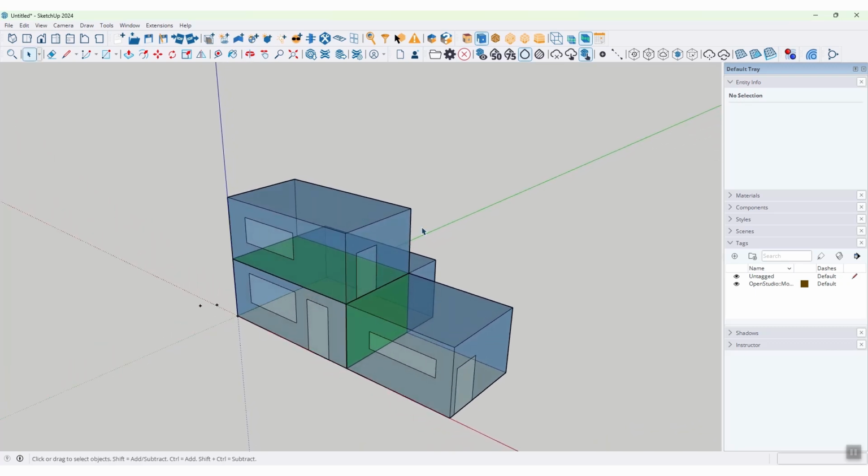After running this tool, we check the model again using the boundary condition render mode. Now we should see that the shared wall is no longer displayed as an exterior surface, and its color has changed to green according to the surface boundary condition. This means that the surfaces of the two spaces have been matched, and the adjacencies have been corrected.